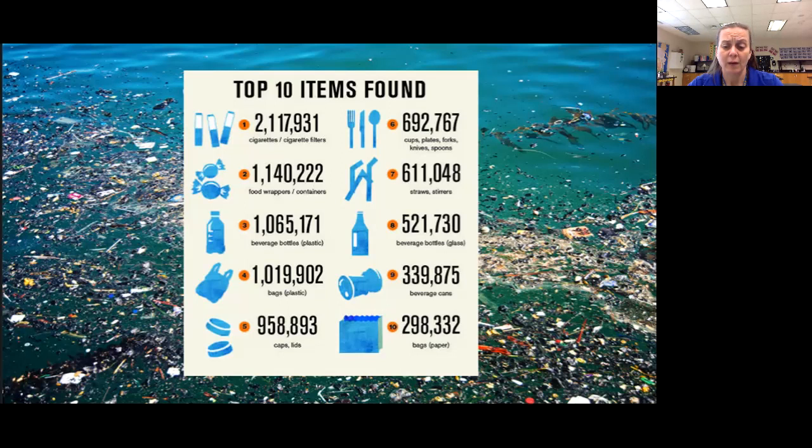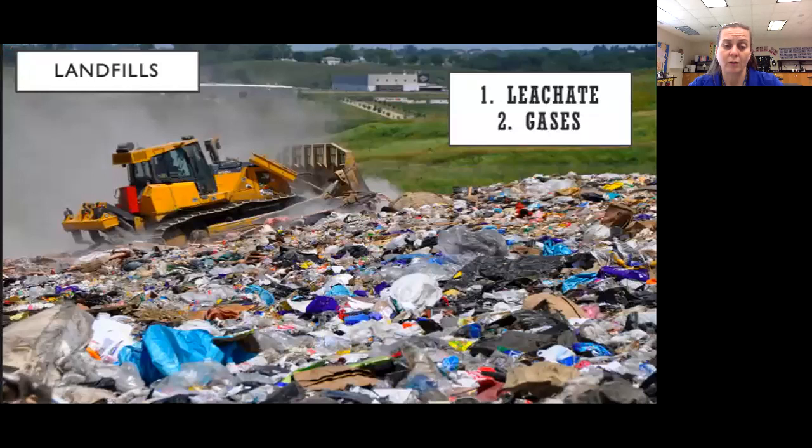Well, in the modern world, we dispose of what we call municipal solid waste. So municipal solid waste, municipal means of the city. So waste from our cities and our towns goes into what are called sanitary landfills. So a sanitary landfill is one that is permitted and follows a certain set of rules as far as minimizing impact on its environment. And we're going to talk about that. So there are really two main issues with landfills. One is what we call leachate, and the other one is gases.